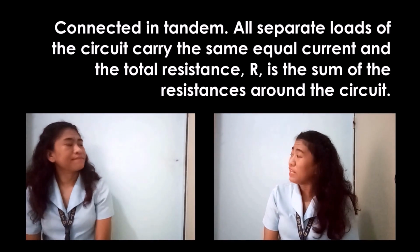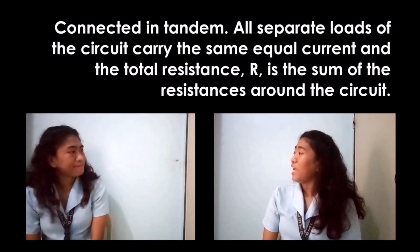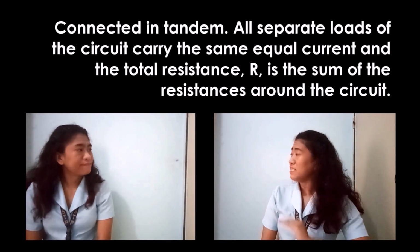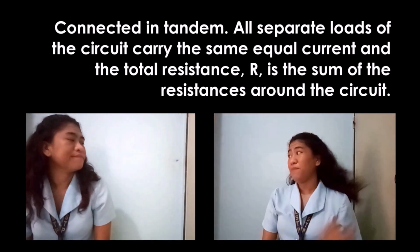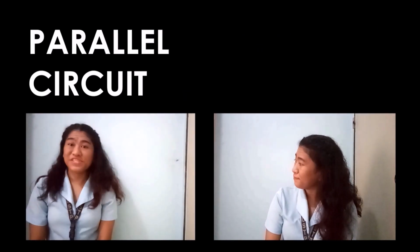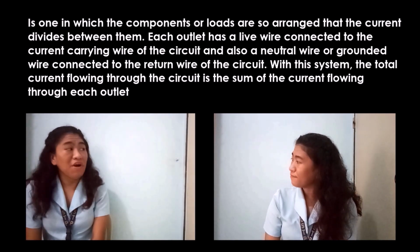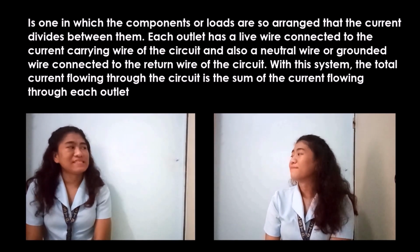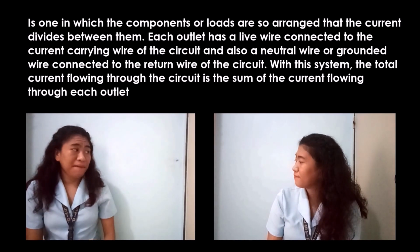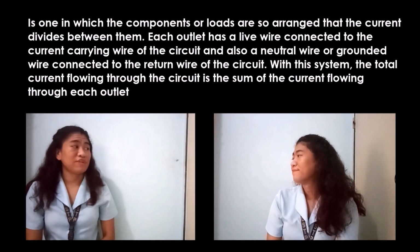Series circuit. A series circuit is one in which the components are connected in tandem. All the separate loads in the circuit carry the same equal current, and the resistance R is the sum of the resistances around the circuit. That's right, and the parallel circuit or the multiple circuit is the one in which the components are so arranged that the current divides between them. In this system, the current that flows through the circuit is the sum of the current that flows to each outlet.